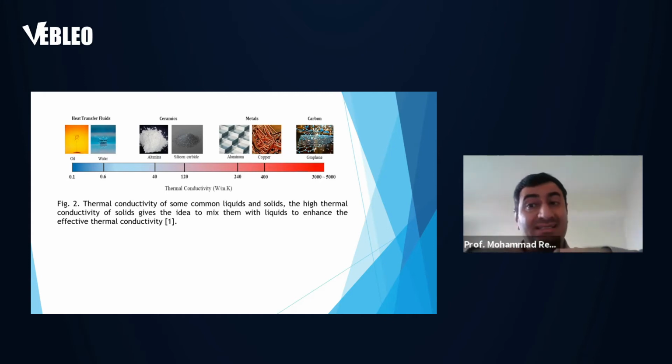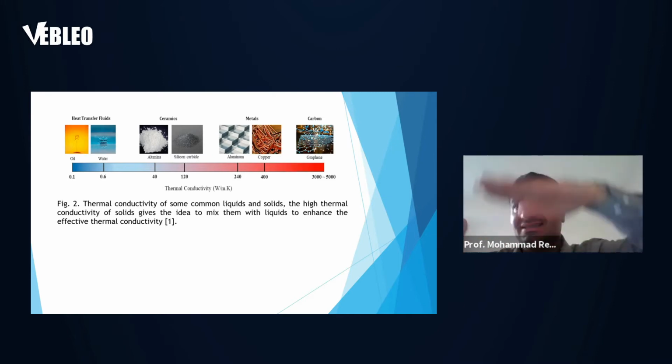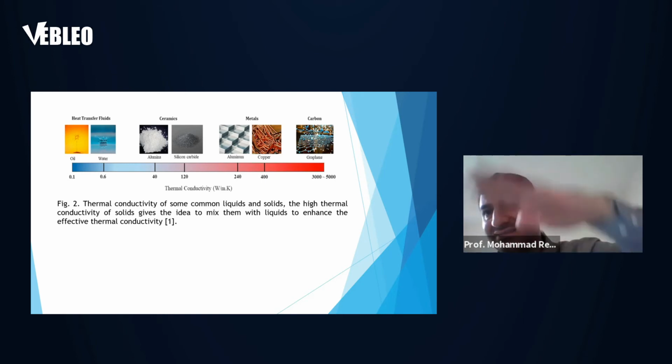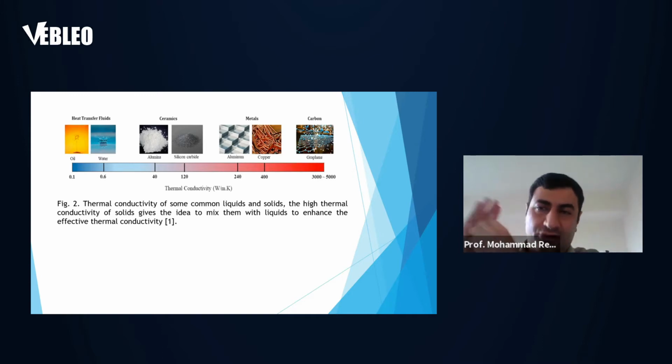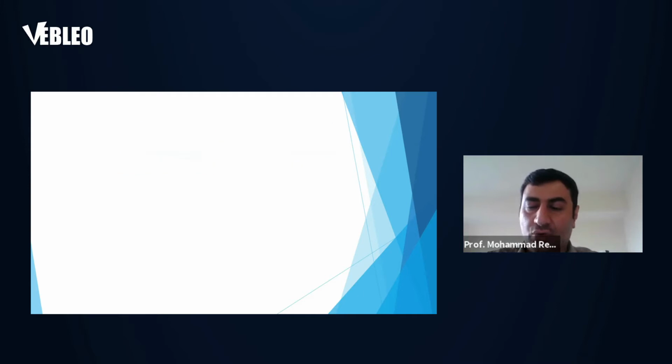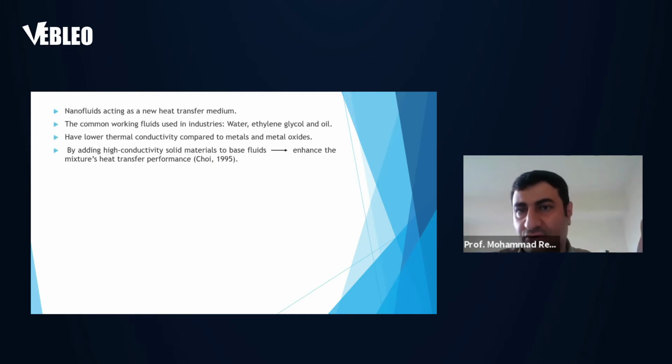Of course, the heat transfer went up, but these particles can clog the pipe, if there is a pipe. Or they can sediment inside the pipe, meaning going down, settling down, and making sedimentation. Over time, the heat transfer becomes worse, and the pipe will again be clogged, okay? So the idea was good, but it didn't work for humans.